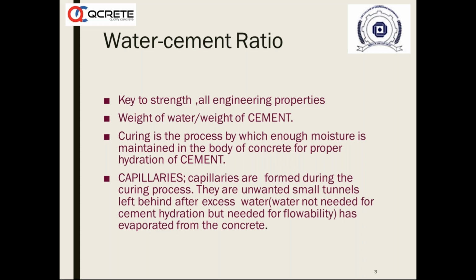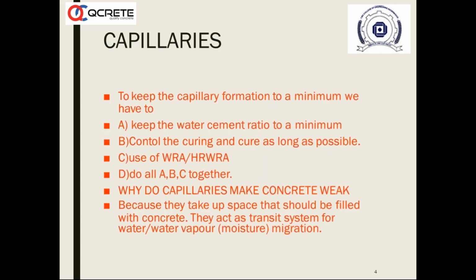And the more the water, the more the evaporation takes place, leaving behind more and more capillaries in the body of concrete. So more capillaries means what happens? The concrete becomes full of voids, and hence there is an effect on strength, there is an effect on durability.